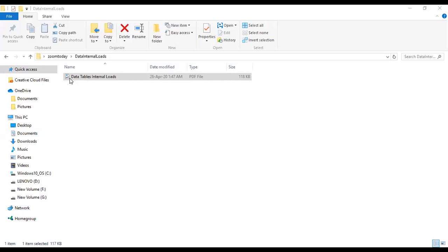You can see it depends on the activity of the person, how much heat he will emit to the air-conditioned space. Heat gains are given with sensible heat gain percentage. Here is total heat gain, and here is sensible heat gain percentage. In some texts, in some handbooks, this may be given only as sensible heat and total heat. So you can calculate by deducting sensible heat from total heat, and you will know the latent heat.